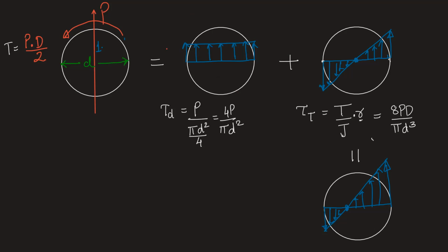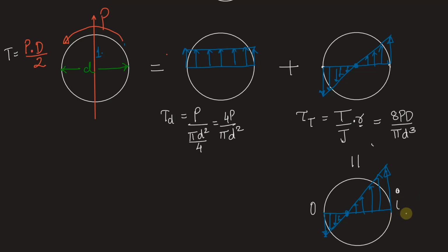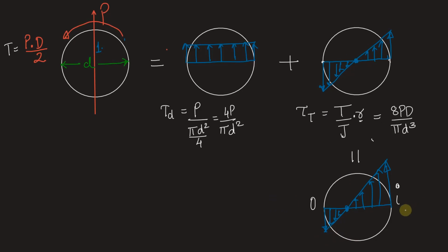But there is also a fourth option given which talks about the stress correction factor on inside edge. So the inside edge will have a higher stress value. This is the inside edge, this is the outside edge. You can check in the spring diagram. When a correction factor is applied to this inside edge due to the curvature effect, because spring is given turns, and due to these turns the inside length is smaller than the outside length, and because of which the inside stress will be higher. There will be a stress concentration in the inside edge.